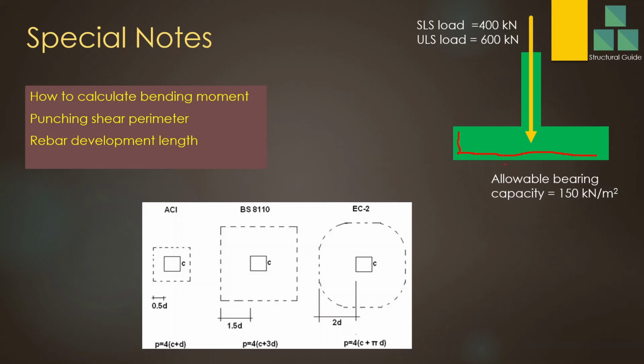The only requirement is that the development length is based on the anchorage length. You should provide the tension anchorage length for this reinforcement. If you do not meet that requirement, you have to bend the reinforcement. I suggest you refer to your relevant standard. With that, you may get a good idea about this development length, and whether to bend the reinforcement or not.